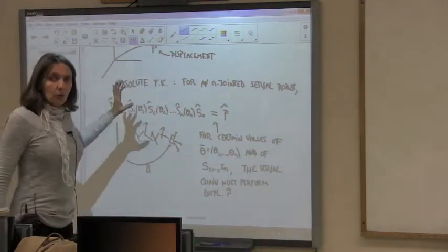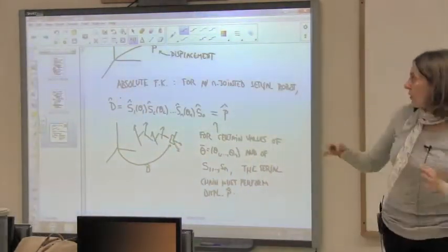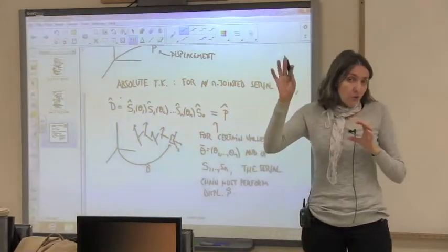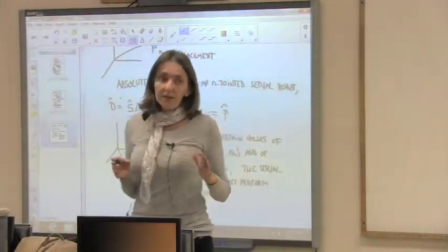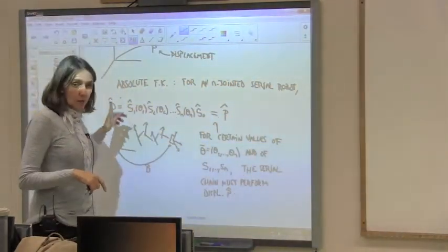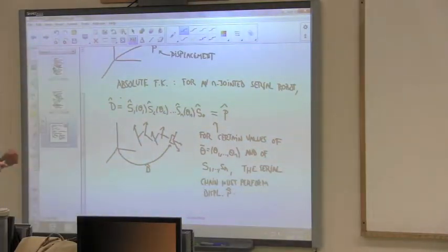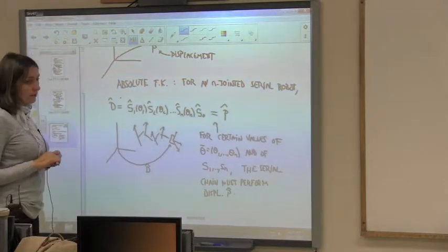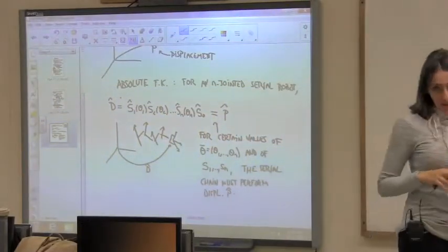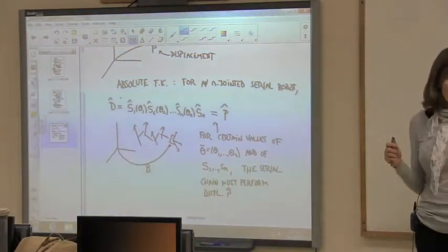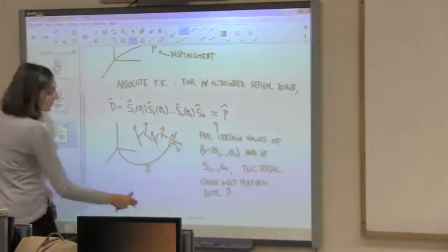So this is exactly what we do for the inverse kinematics. Remember, we take the forward kinematics of our robot, we equate it to a given position we want to reach, and we solve for the angles. You can think of this as a generalized inverse kinematics in which you have to solve not only for the angles, but also for the location of the joints. Everything is unknown. So it's a little bit more complicated. I mean, inverse kinematics is sometimes complicated already. The synthesis is, of course, much more complicated. You have a lot of variables, and you get very nonlinear problems.